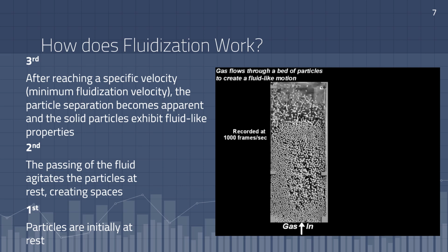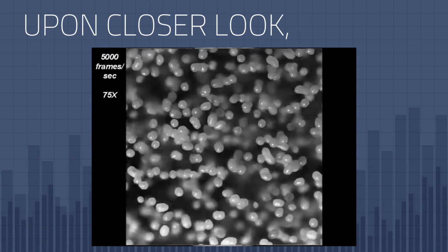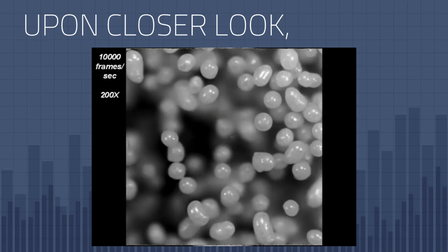However, as the fluid rises through a bed of particles, the pressure drop is observed to increase, caused by frictional resistance due to the contact of the fluid with the particles and pipe walls. And upon closer look, it can be observed that the particles are colliding and bouncing off each other.